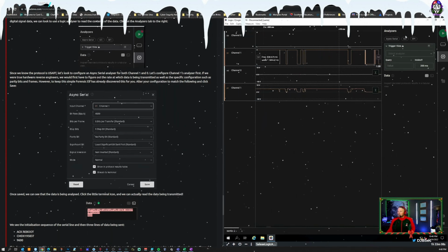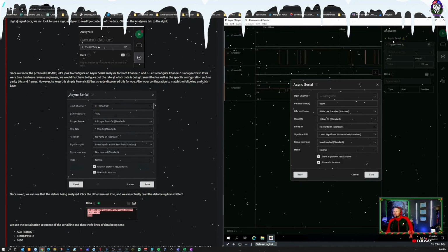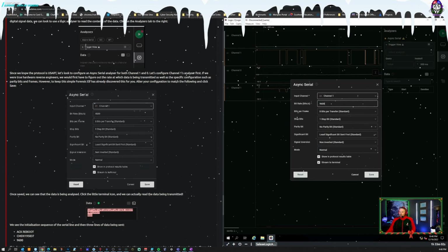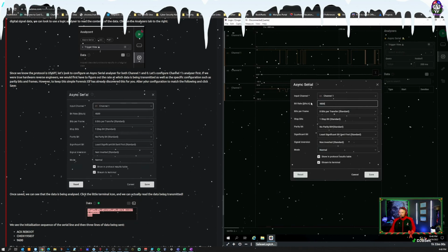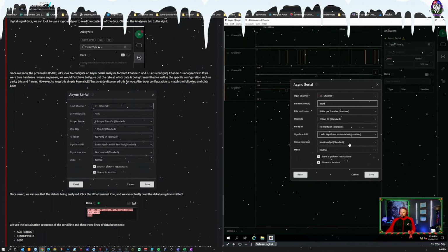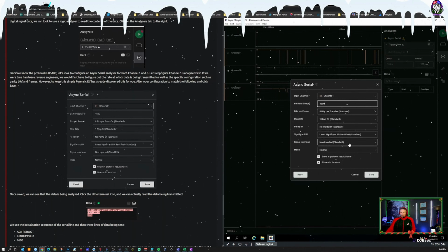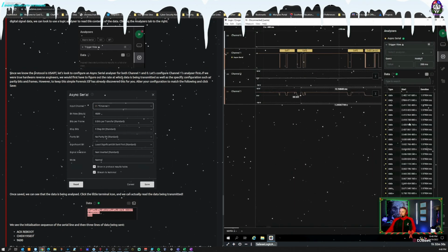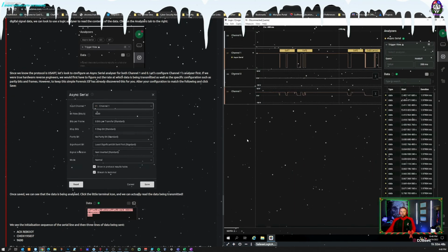All right, so let's click Async Serial. And we're going to do channel 1 at 4800. I think we've got 8 bits, none, 1 stop, no parity, least, none. That should be good, and let's hit Save. Ooh, look at this. Now we've got data in this bad boy.